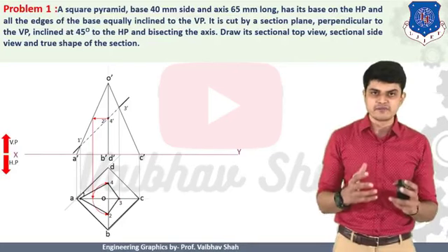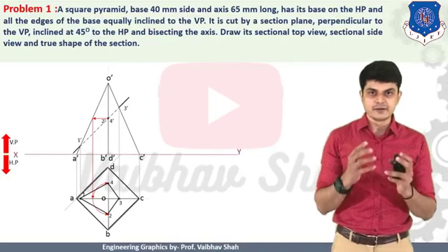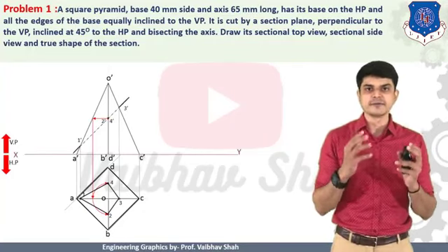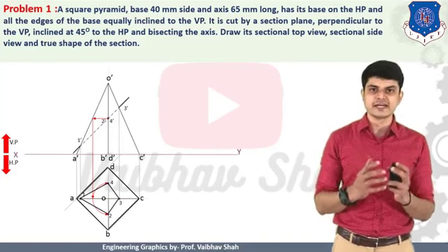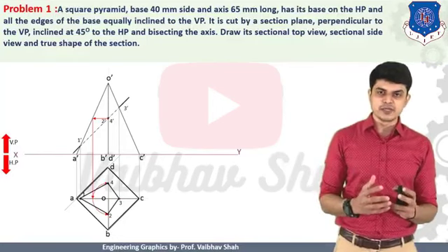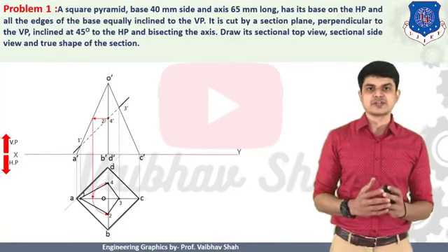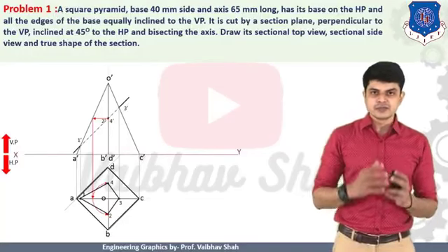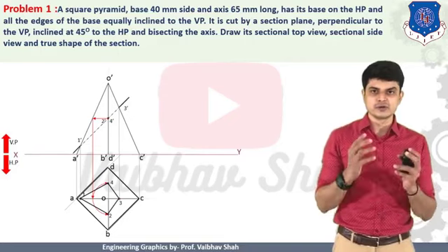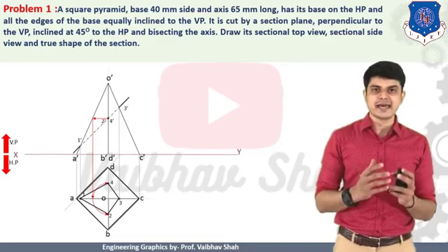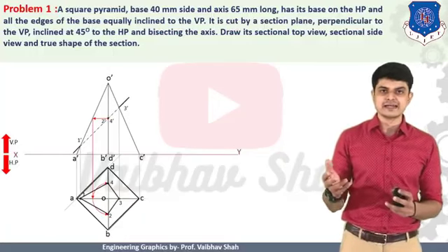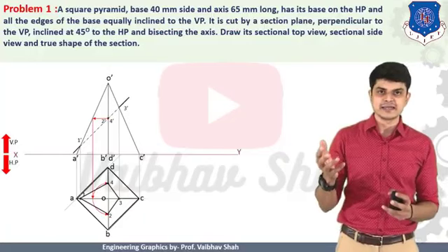When we connect these points, we will have one object generated. And remember, we have cut our object at 4 points. That means the object generated will have 4 different points. When connected, it will give one polygon of 4 sides, as you can see. Now, after getting this polygon, we have the actual cut section generated in your top view. So thereafter, we have cut and removed the top portion of your object. Now we should draw the remaining portion by a darker line, which will be our actual object after cutting. So we should make the remaining object by a dark line like this.